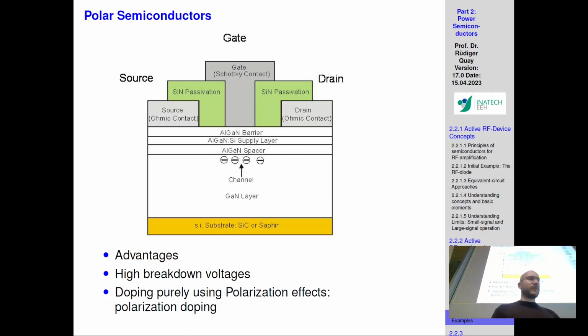And you don't have doping in this case, but you just have a certain alignment of different bandgap materials, and this alignment twists your valence and conduction bands, so that at points in the material, in these bandgap transitions, you generate carriers, you diffuse carriers, and these carriers are polarized with spontaneous and piezoelectric polarization.